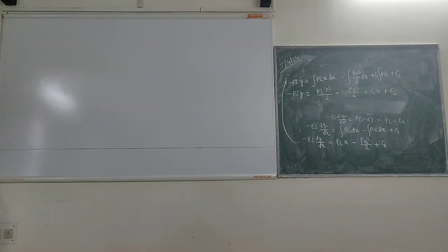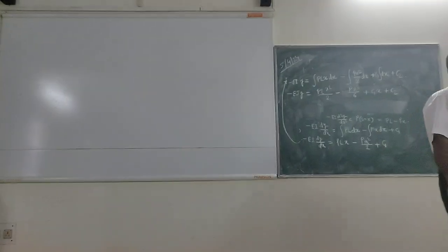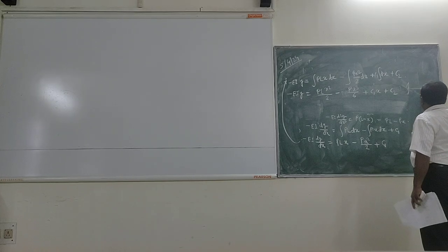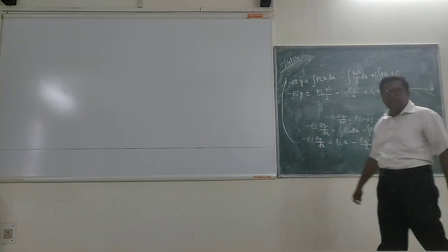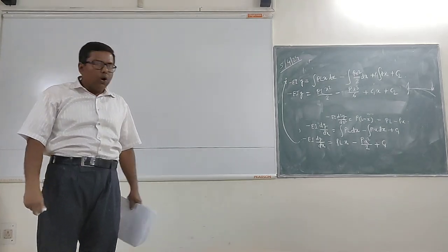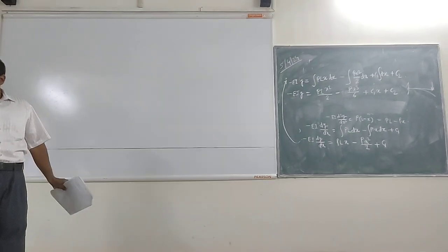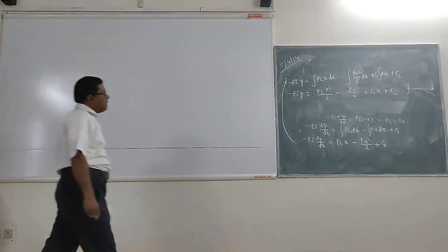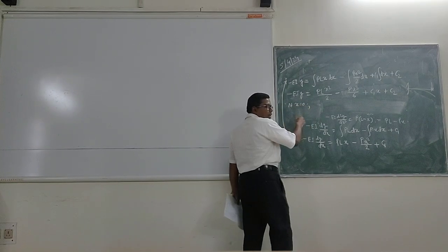No? So now you put the boundary conditions. What are we considering? We are taking a cantilever beam. So what will be the cantilever beam boundary conditions? Just now we have understood. At x equal to 0, y equal to 0. And at x equal to 0, dy/dx will be equal to 0. Clear? So you put the boundary condition at x equal to 0.